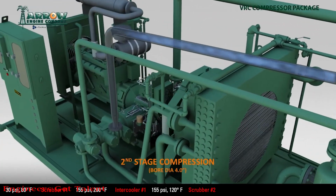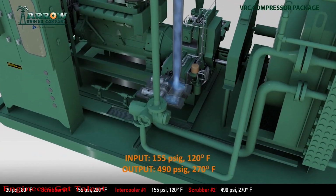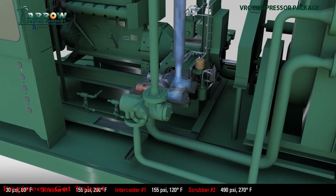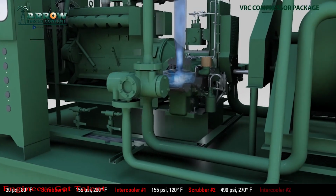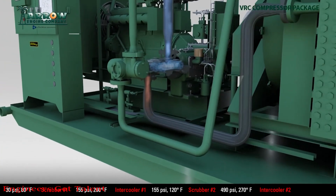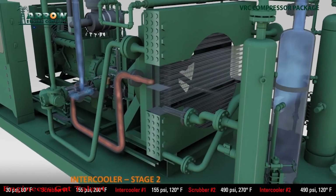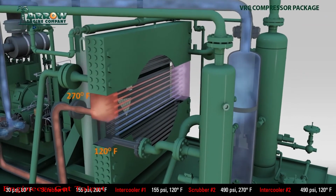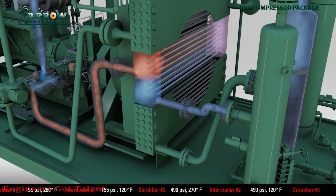The second stage of compression increases the pressure to 490 psi and the temperature also heats up to 270 degrees. From there, it's back through the cooler to get the temperature back down to 120 degrees. With more pressure and cooling, there's more liquids that will fall out in the last scrubber.